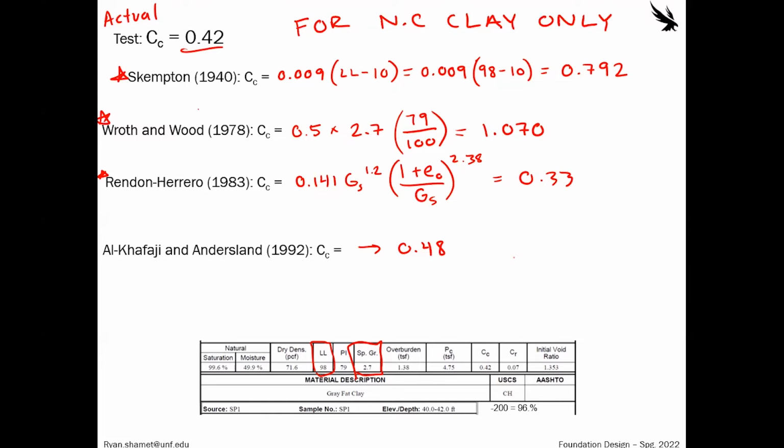Because again, here we have our current sigma prime equal to 1.38. And then from here, our pre-consolidation pressure is 4.75. So therefore, this is an OC soil, over consolidated soil. So that's what I was talking about last week.